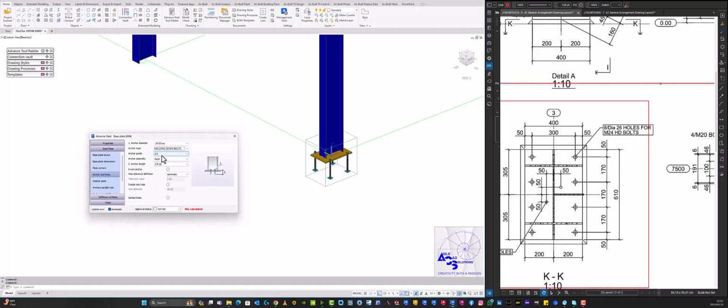And the grade, remember, according to our structural steel notes, the grade is 8.8. So click the drop down arrow. There is our grade 8.8. Assemble anchor. This is how your anchor is going to be assembled. And then the length of the anchor. In this case, we're not given how long the anchor is. But if your anchor is 600 long, you can just change there and say 600. If it's 500 long, you can change it to 500. So it depends on how long your anchor is.